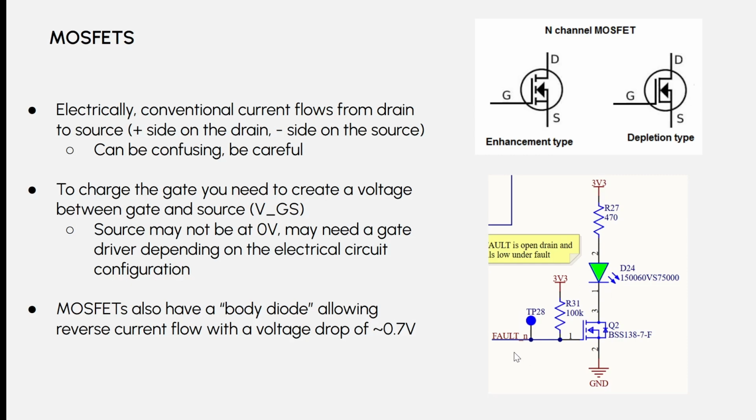But when there's a fault condition, it basically pulls this pin low. That's all it can do. It can't pull it high, but it pulls it low. Because 100K is a very weak pull-up, it will very easily pull low. That brings the gate to 0 volts, and then it opens the circuit so the LED turns off, indicating there's a problem. So yeah, the main use for MOSFETs is as switches. Microcontrollers are literally just millions of MOSFETs put together in a specific way. CPUs are also just billions of MOSFETs.